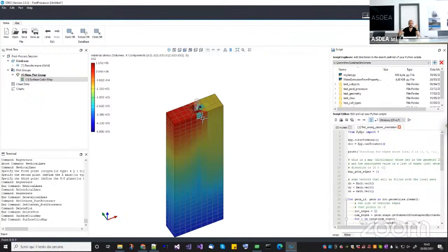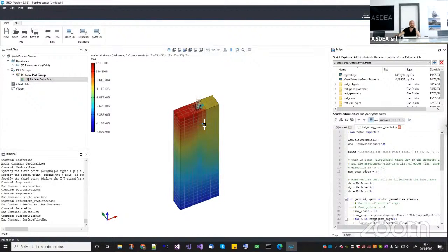In fact, if I just move the contact before the excavation, the program couldn't find any convergence. So it is actually a mess, and that new contact element will be very useful. Other than this, we've added a new element, which is used to embed an element inside another. It will be very useful for micro modeling of concrete structures, but also to attach incompatible meshes. And this will be the topic of the next webinar.